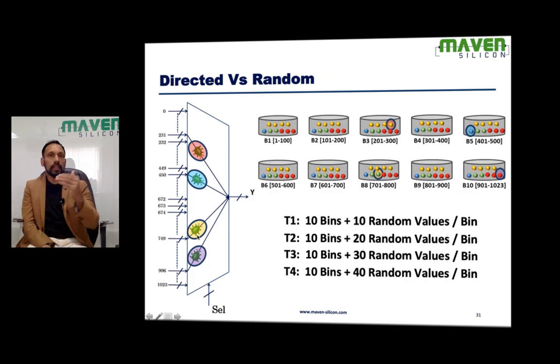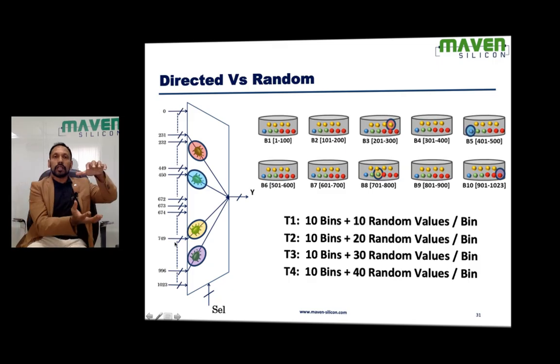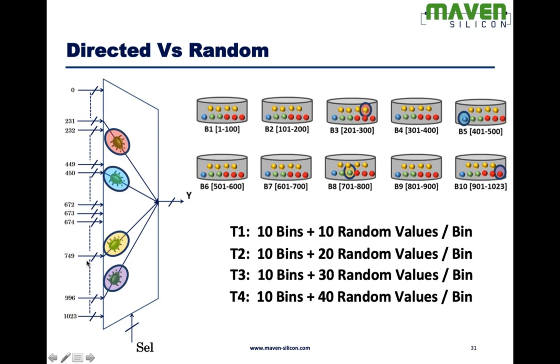Nobody is going to give you a month of time to verify a multiplexer. If that is the case, then probably you might be able to assure 100% verification. Nobody tries for 100% verification. And when it comes to doing this kind of simulation, we focus more on design functionality. Whether the multiplexer has been implemented as per specification. Whether the functionality is retained in the multiplexer. That's what we try to prove during simulation. But while proving, we also look at, are we getting bugs? That's how the simulation happens.